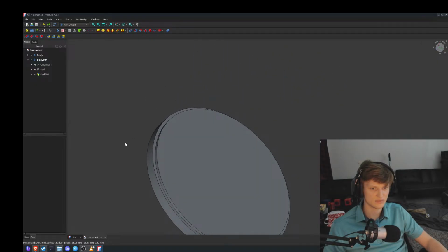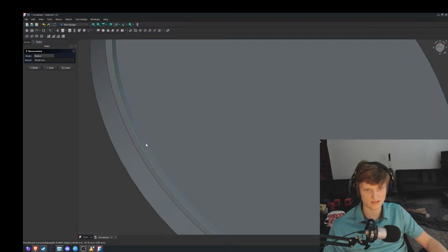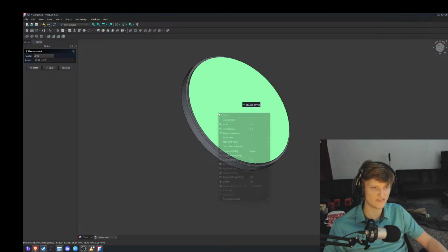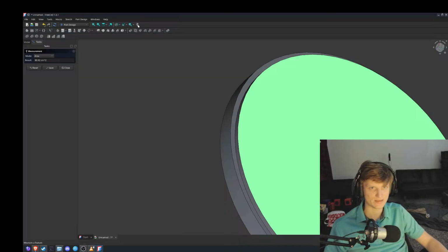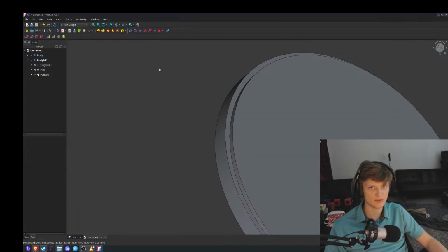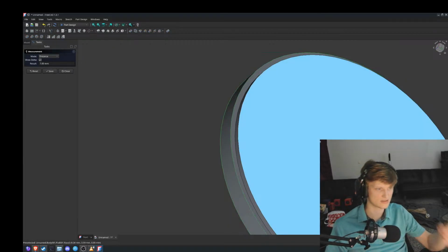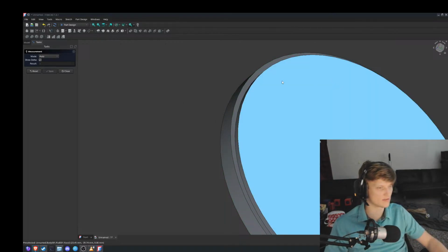Okay, now I need to basically. Okay, what's the measurement between that line and that line? It's 2 millimeters. All right, we want to take this face right here and just this down. Wait. We're getting a groove here. We know exactly what we want to do. We need to do this and this. That's not what I'm looking for. I want this point and this point. That is 7 millimeters. So we need to extrude down 7 millimeters. Perfect amount to extrude downward.